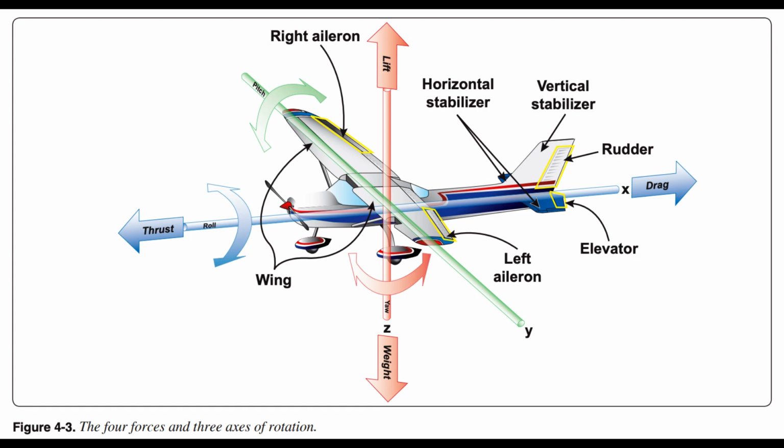The distance, total, between the skin surface and where free stream velocity is reached is called the boundary layer. At subsonic levels, the cumulative layers are about the thickness of a playing card, yet their motion sliding over one another creates a drag force. This force retards motion due to the viscosity of the air and is called skin friction drag. Because skin friction drag is related to a large surface area, its effect on smaller aircraft is small versus large transport aircraft, where skin friction drag may be considerable.